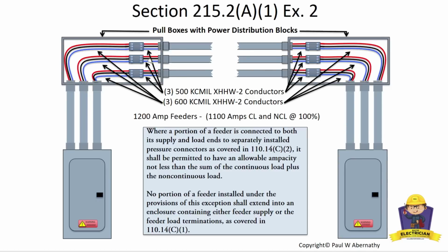But that is quite a bit when you talk about a certain length, and that could be a good cost savings to you. Remember that you might have voltage drop involved, so you have to take all those things into consideration. You're still going to have your ambient adjustments, and everything else. But at least taking option A into effect, it's saying, okay, don't worry about the extra 25% for this application.